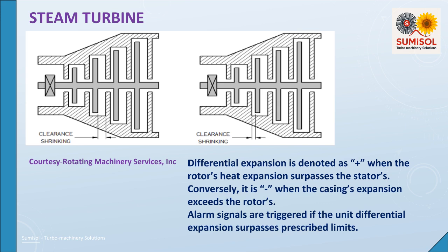The rotor position is fixed at the thrust bearing to restrict its axial movement within the turbine casing. This means the rotor will thermally grow away from the thrust collar and contract towards the thrust collar during differential expansion. This is important to remember when setting rotors and determining startup and shutdown time periods.